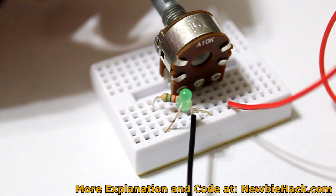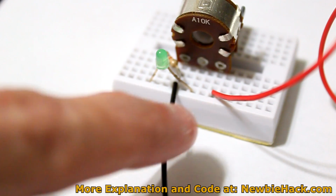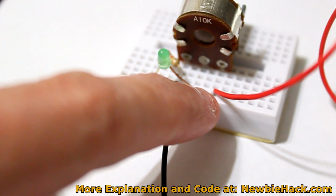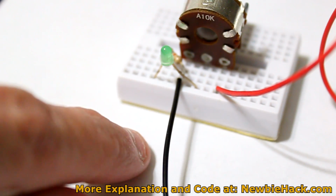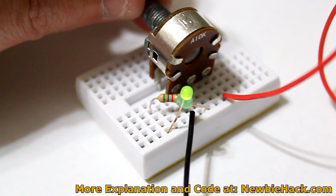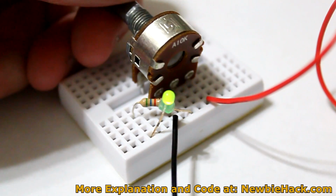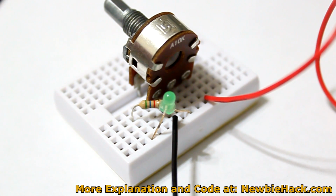The same thing can be shown with an LED. The LED is going through a resistor, connected to the middle pin of the potentiometer, and then it's connected with a resistor to the outside lead. As we turn up the potentiometer, you'll start to see it get brighter and brighter. And then as we turn it down, it starts to dim. With PWM, we can do the same thing with the microcontroller, and the microcontroller does this by pulsing its 5 volts very, very fast.